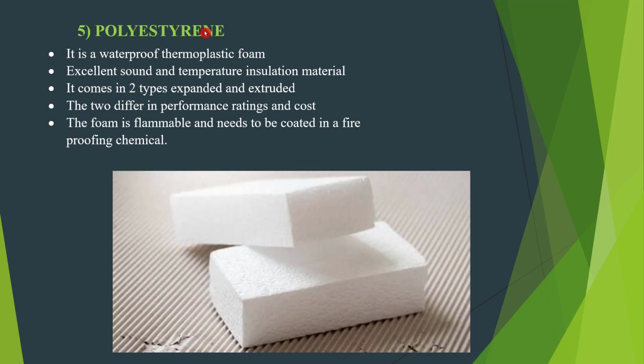Next one is polystyrene. It is a waterproof thermoplastic foam. It has excellent sound, so an acoustic option is also there. Excellent sound and temperature insulation material. There are two types, expanded and extruded. They differ in performance ratings and cost, and this foam is flammable, so you have to take much care. It is not good for very high temperature and needs to be coated with a fireproofing chemical before the application.